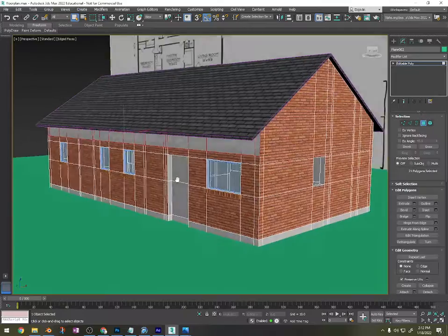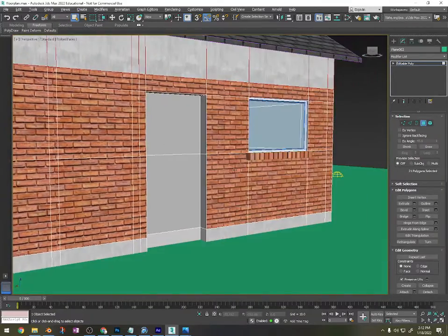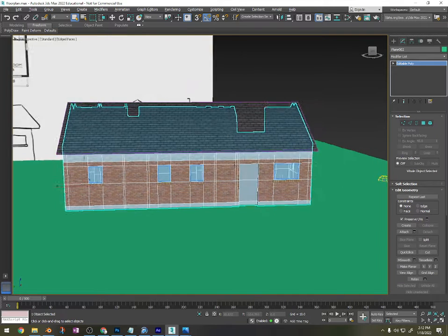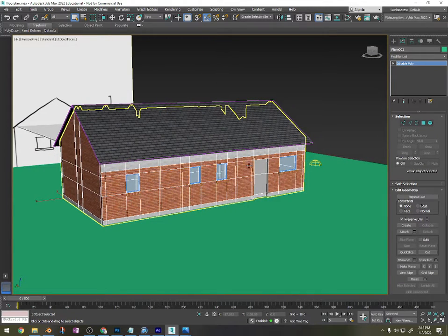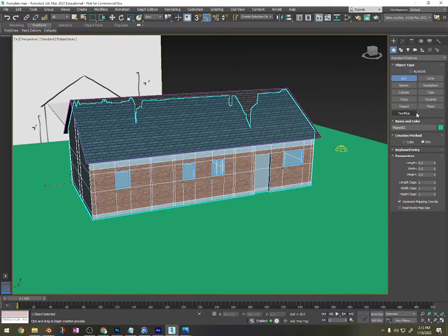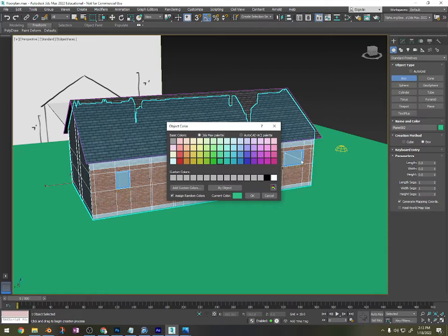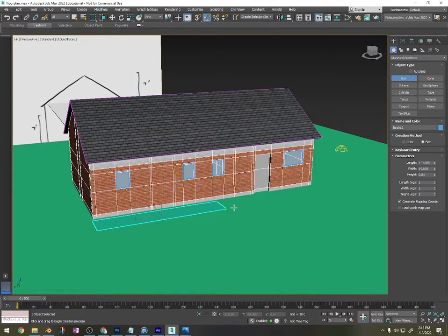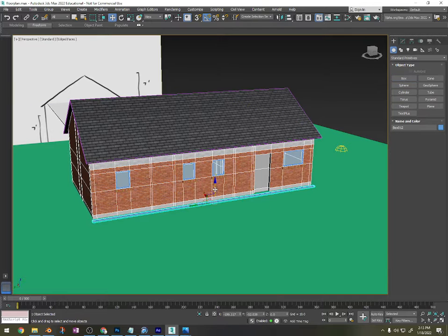And now what we're going to do in here is add a chimney and some gutters. So first, let's do the gutters. This is very easy. We're just going to create a very simple generic gutter. So I'm going to click on the plus sign. I'm pressing P to go into perspective view, and I'm going to make a box, and before I drag it, I'm going to click on here and make it white. And first I'm going to eyeball the length of the house, and about that thick, and I'm going to press W and go ahead and move this up.